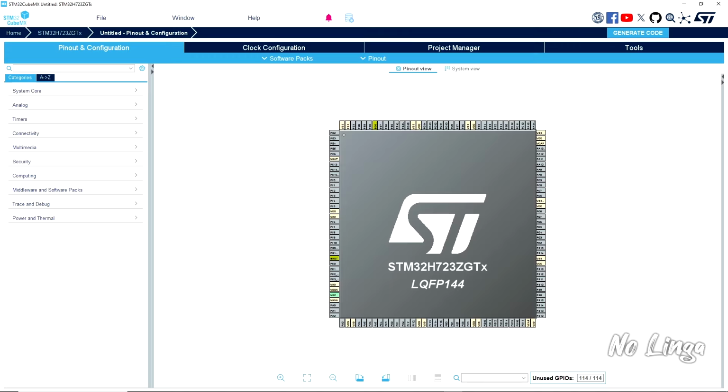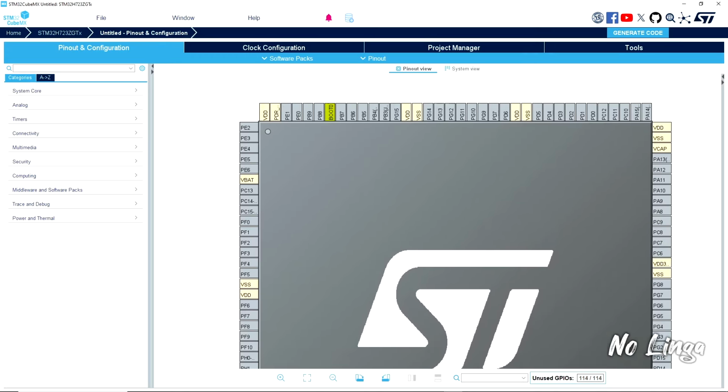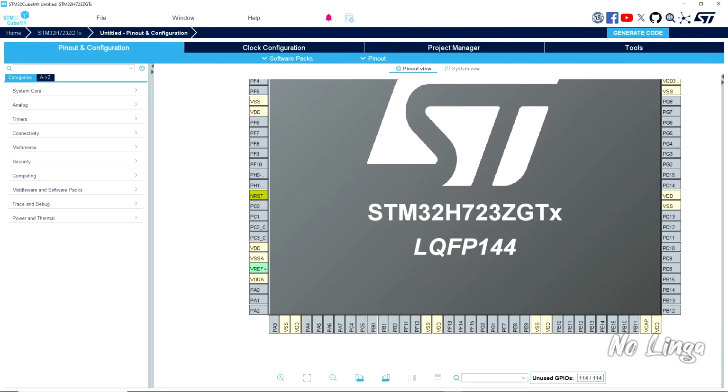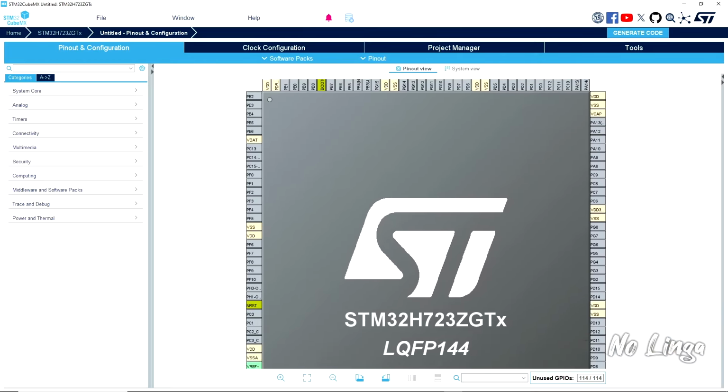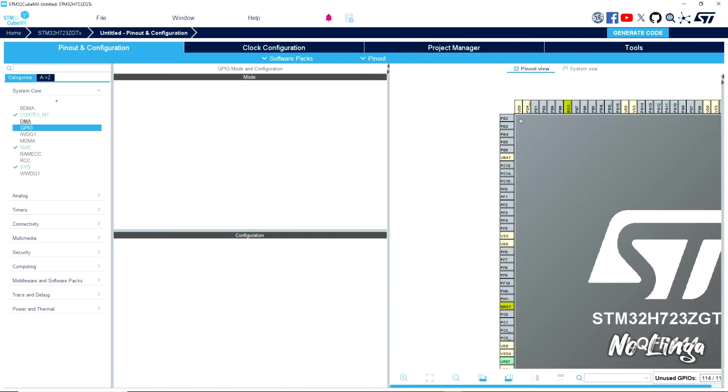Yes. Once you're in the program, you can actually zoom around and look at the pin layout of the microprocessor or microcontroller, and from here you will be able to go ahead and start assigning the functionality for the pins that you want to choose. We'll go ahead and configure the GPIO, and we're going to select a few pins that we're already familiar with, especially on the expansion board that I designed.